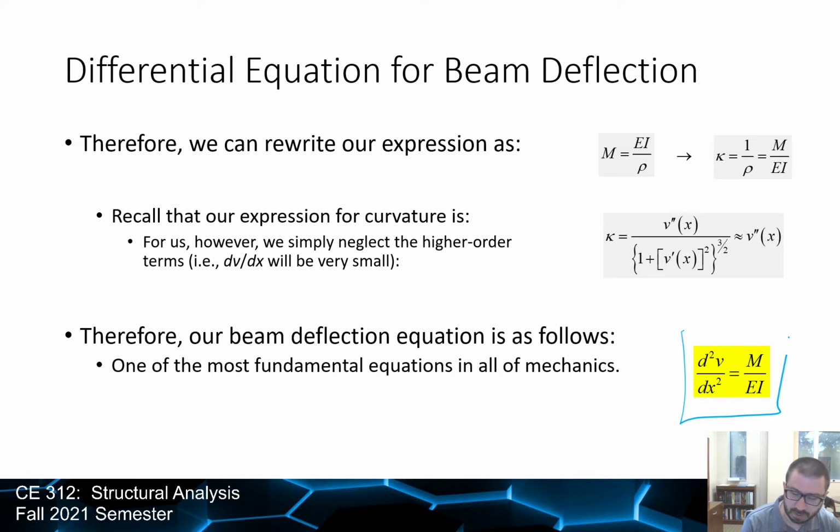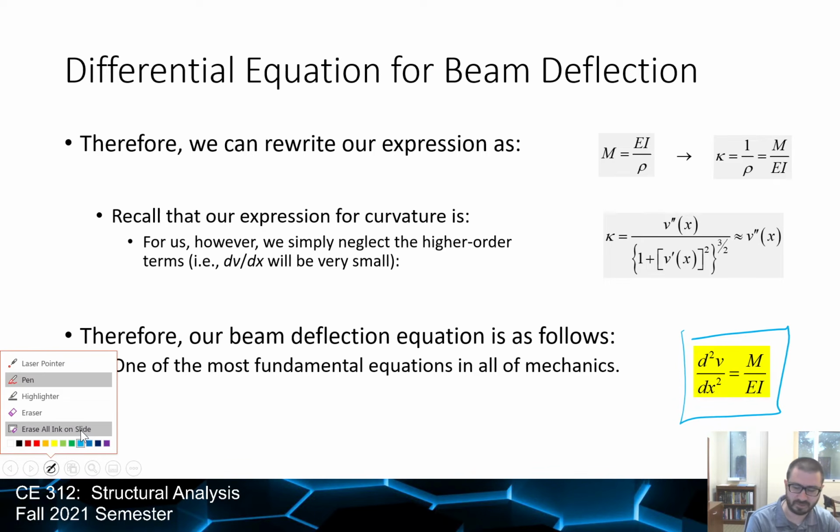This is arguably one of the most fundamental equations in all of mechanics, the idea that the second derivative of deflection is M over EI. And we're going to use this expression to develop our method of virtual work.